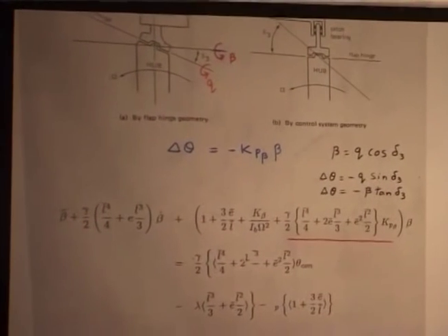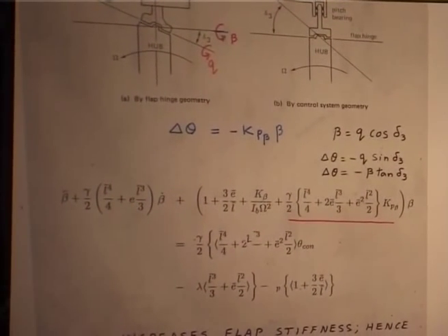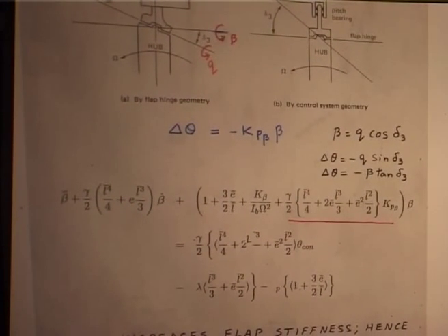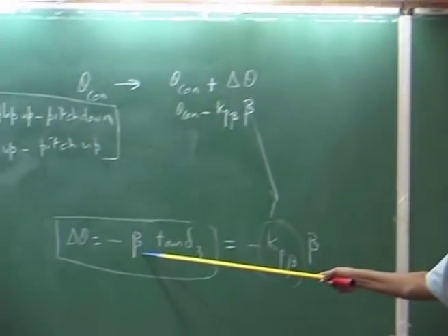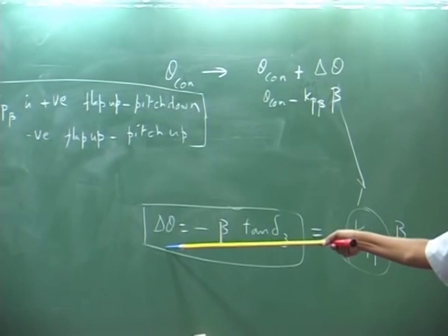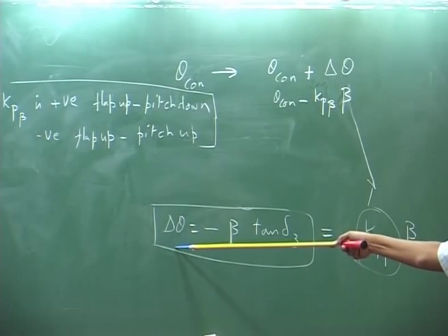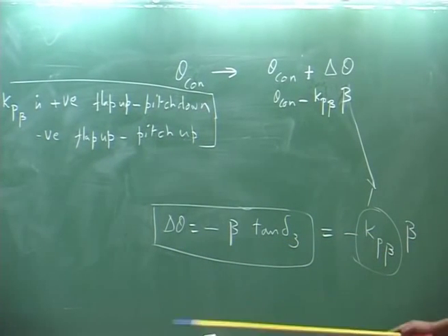It is very powerful in the sense of influencing the aeroelastic stability, even though these tilts are small. Now I will come to the delta 3, in the they use 45 degrees, okay. That means tan delta 3 is almost 1, right. So, tan 45 degree is 1. So, whatever it moves through 1 degree flap, 1 degree reduction in pitch. So, that 45 degrees they put.